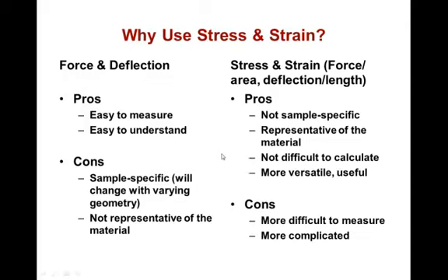The cons of the stress and the strain is that they are more difficult to measure, so we don't measure them. We use force and deflection and then do the calculation, and they're a little bit more complicated, but nothing that we can't handle.